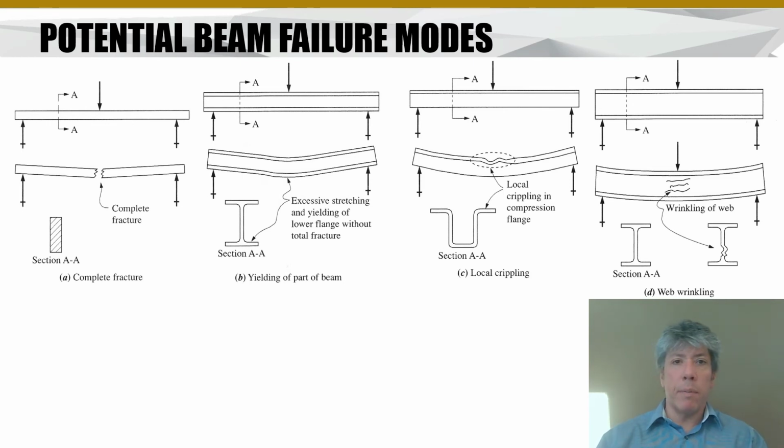This makes an efficient beam, a beam that can carry a lot of load. Another really important thing to understand about this stress distribution is that the integration of this stress across the entire cross-sectional area has to generate the moment M. So if you add up all the little stresses in all of its little areas, which is what integration does, the net result of all this stress over the cross-section has to be the moment load at that section of the beam. So that's a constraint for the stress, and that's why the stress and the moment are related to each other by the equation you saw.